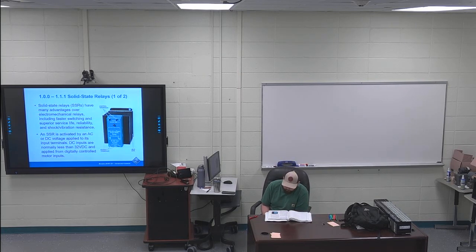110, solid state relays. First two sentences are highlighted. The solid state relay, SSR, has many advantages over the electromechanical relay, EMR. It has longer life, higher reliability, higher speed switching, and high resistance to shock and vibration. So there's no moving parts.